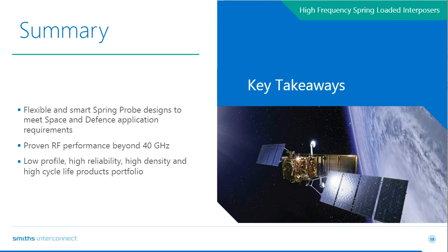Another application I can think of is one where we had an SRS shock. It didn't have to be operational during the shock, but it had to be functional before and after that shock. And in that particular case, it was 2,200 Gs that it passed as well.